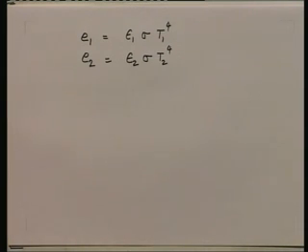And as I said a moment ago, let me repeat, I am going to analyze what happens to the radiation which is emitted by one surface. Any radiation emitted by say the surface 1 or the surface 2 will go to the other surface, get partly absorbed and partly reflected, will come back to the original surface where it will get partly absorbed, partly reflected, will again go back to the next surface, partly absorbed, partly reflected. So, you will have successive reflections and absorptions as the radiation is bounced back and forth. We want to analyze in this manner. So, let us now look at the surface 1 and see how the radiation is absorbed and reflected.